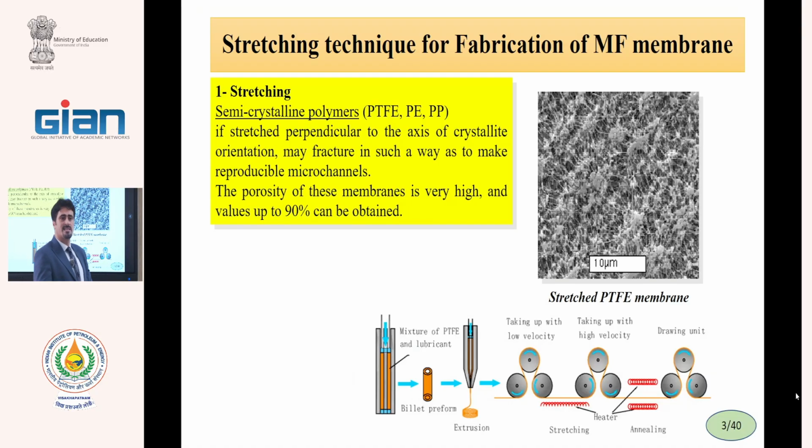After melting, we produce a film or a fiber, hollow fiber, okay? And when we coat this melted polymer on the surface of a glass, the temperature should be reduced. And with reducing the temperature, the polymer solution changes to solid, okay?